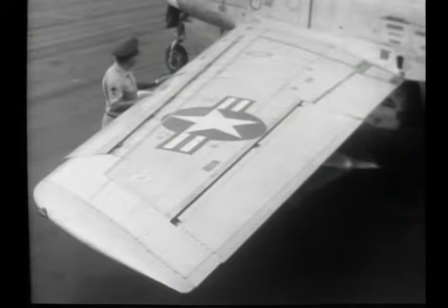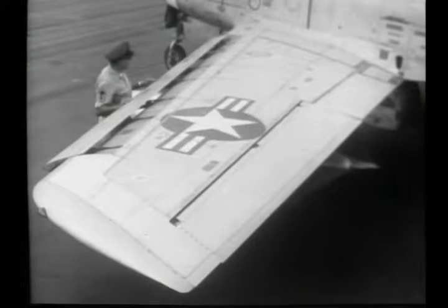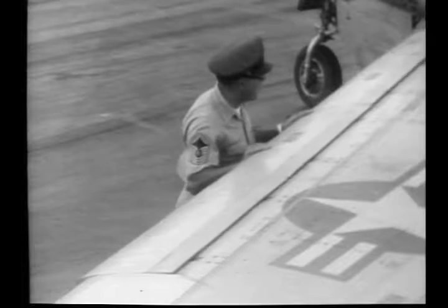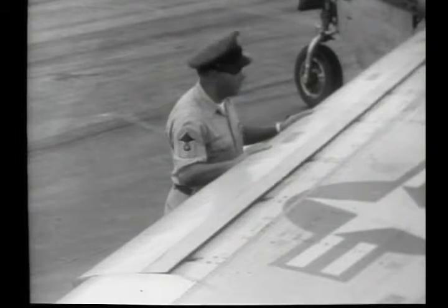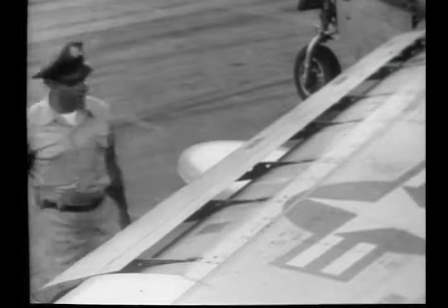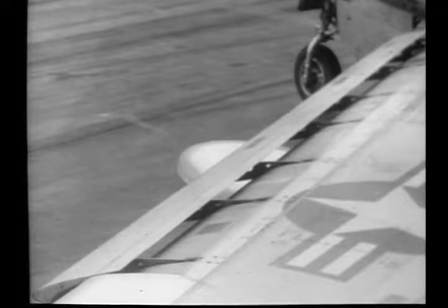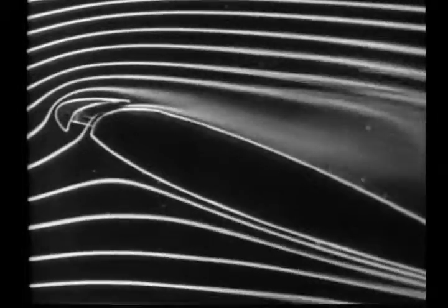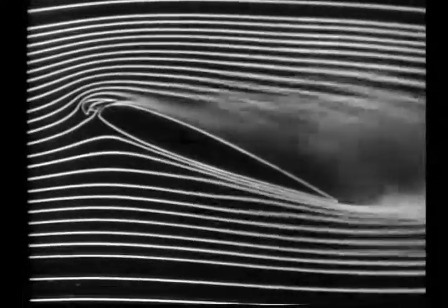Blowing jets directed into critical areas are also useful. Frequently, these can be created by utilizing the pressure difference that exists on the aerodynamic bodies themselves. The leading edge slat leads air from a region close to the stagnation point through a converging channel and ejects it at high speed at a point of low pressure on the upper surface.